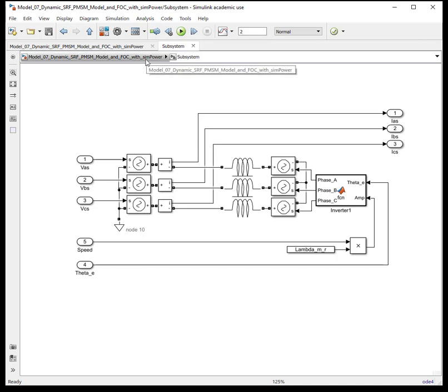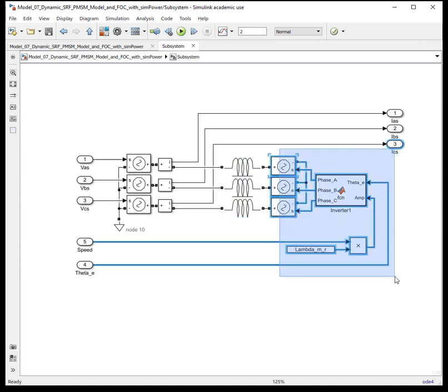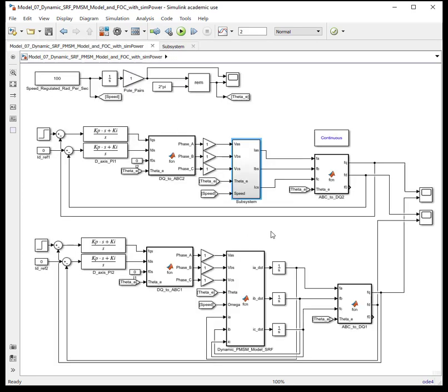And that's basically it. So you have your voltage fed in to your circuit, to your motor. You have your inductance and resistance elements here. You have your back EMF terms here. And then we have our current measurements here, because this is where the current is flowing, right? The currents flow through the inductors, and that's basically it. So it makes it very convenient to build a model.